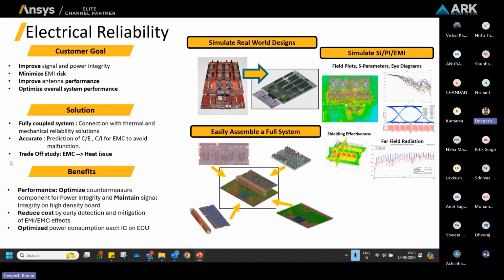You can perform overall PCB signal performance, cable performance, and trace performance as a channel with a high data rate and high speed. When I talk about high speed, I mean digital signals. You can check the emissions. You can use shielding effectiveness to suppress emissions going outside your domain, I mean from the chassis or any supporting medium. We can use this simulation analysis quite effectively.